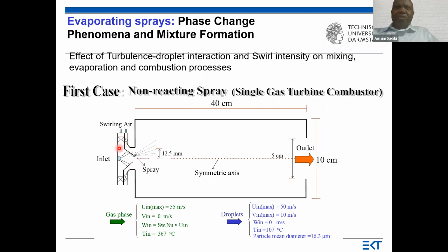So we have our sphere here, it is air assisted. We have here the film, which is built on this lip here, and then through the shearing due to the air, we get the spray, the atomization at this position.